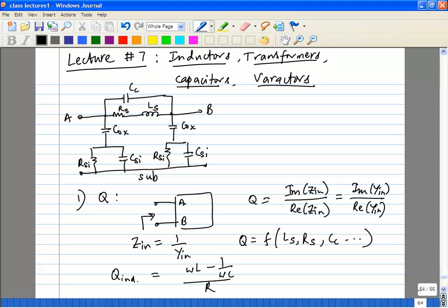So if we use a lower metal layer, the metal layer is getting closer to the substrate, so that capacitance is increasing. The metal layer to the substrate capacitance is actually Cox. CSI is actually to model